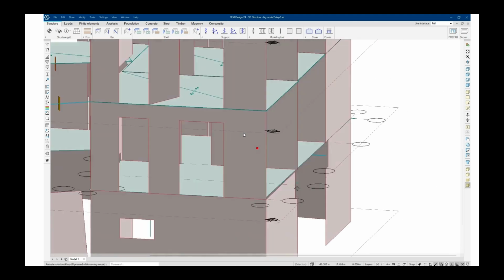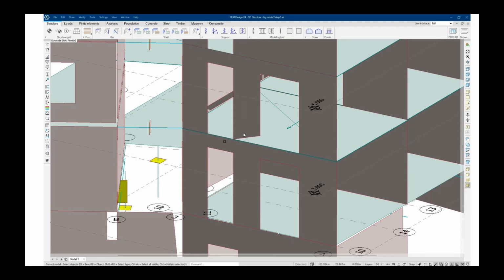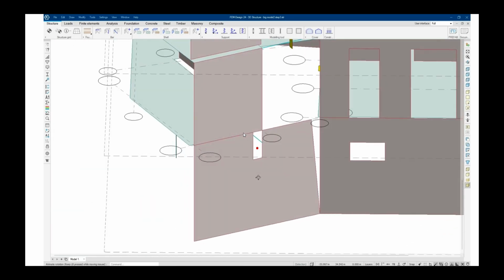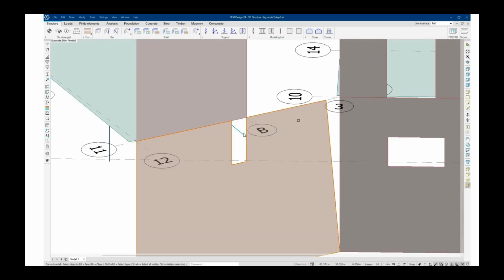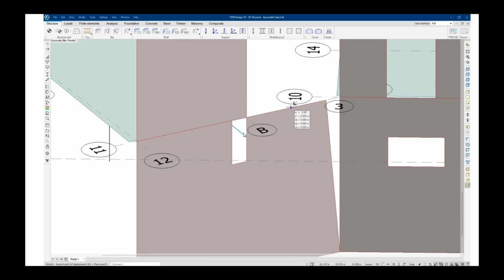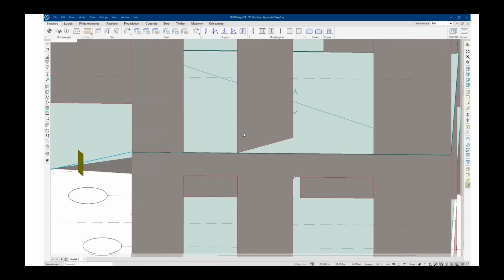But we noticed that there are a few points where the software hasn't fixed anything. Like this is one example, and this is one example. The problem is that it was unable to correct because some parts of the elements were smaller than 30 centimeters. Then this edge goes to zero, and that's not allowed, like the connection at the line B. But if we give it a hint, let's make this distance smaller and try to fix the same element with the smaller tolerance.